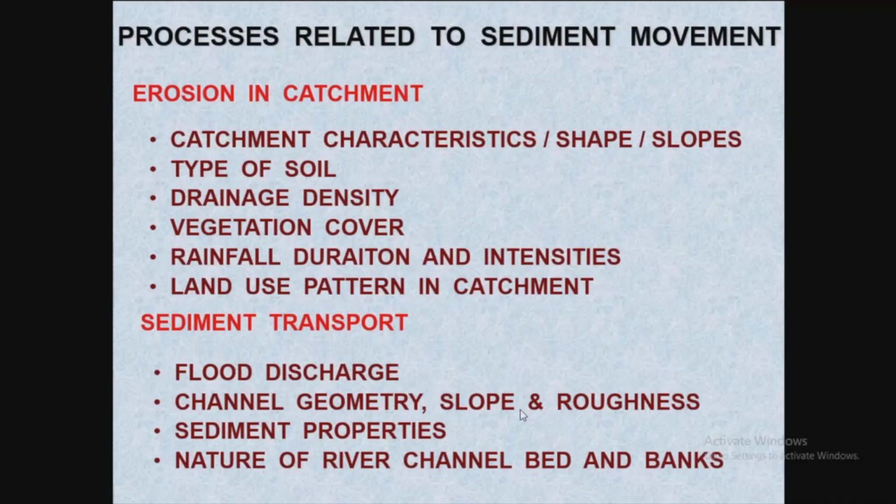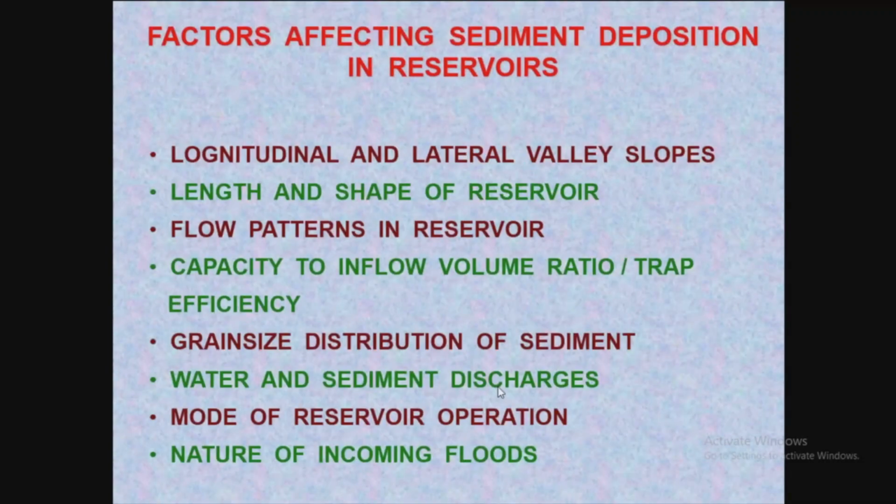Now, what are the factors affecting this sediment in the reservoir? So lateral and longitudinal valley slopes are a major factor. If the longitudinal slope is high, then more sediment will come in within a short time, and if it is flattened, then less sediment will come. And the length and shape of the reservoir is also a very governing factor.